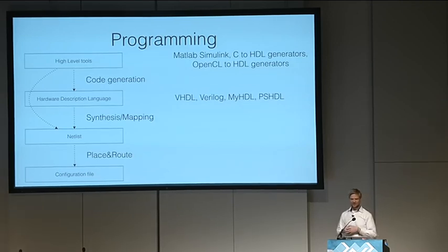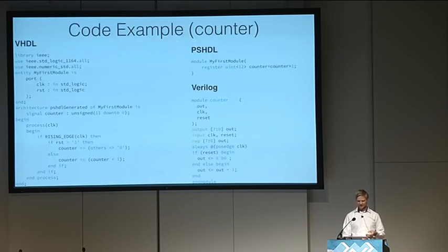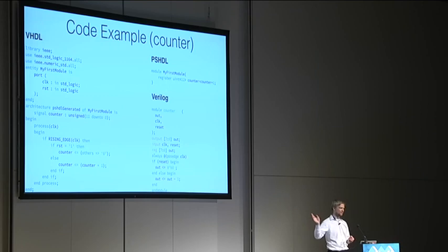So after that you have your configuration file, and you realize that this is not called an executable because it's not. It's configuring the resources within the FPGA to do whatever you told them to do, or do something entirely else if you have a tiny mistake in your hardware description language. By the way, in PSHDL, what you simulate is what you get, which is not true for VHDL or Verilog. If you're running simulation in Verilog or VHDL, it might be what you're getting in hardware, but it might not be.